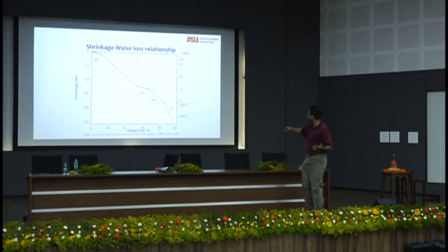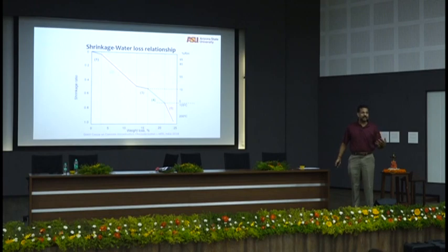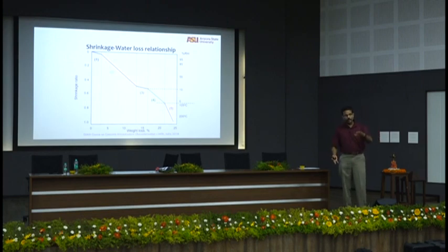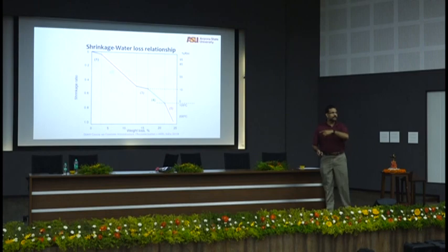Right? 11% is the relative humidity at which I said you can take almost all water off. Really, really dry. But again, an ambient relative humidity of 15% does not mean concrete relative humidity is 15%. They are two different things. Concrete will have a much higher relative humidity, but because the ambient relative humidity is much lower, there is still mass transport happening during all this summer, right? There is still chance for internal stresses and cracking all this time. Whereas these pavements, parking lots and slabs should never crack.